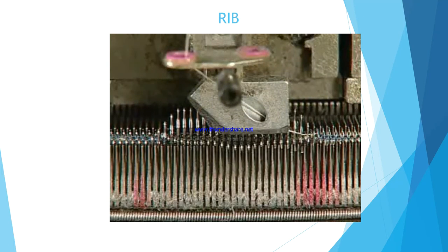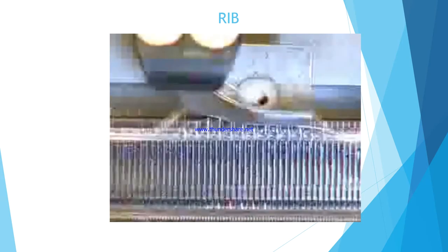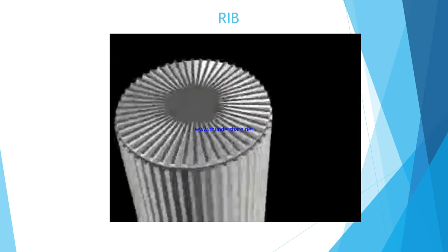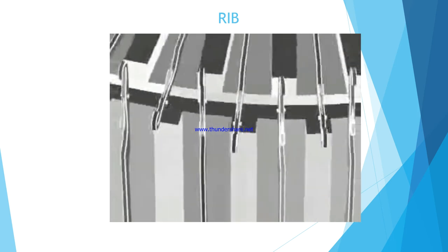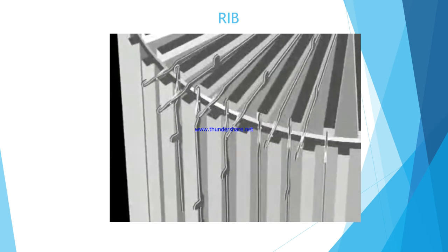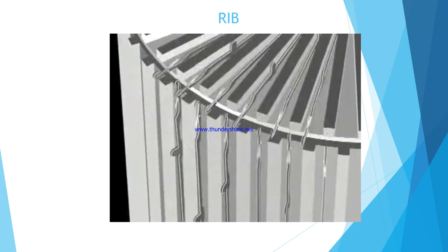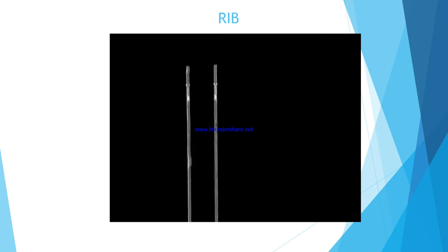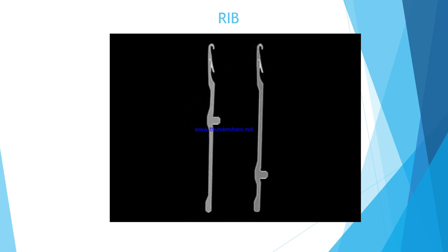On a knitting machine, needles are gated or spaced in the dial and the cylinder in relationship to each other. With rib gating, the 2 sets of needles are not directly opposite each other. The needles of the cylinder are between the needles of the dial. Here you can see how both sets of needles can knit at the same time without touching or hitting each other. Although all needles have the same length, the butts are in 2 different locations, which activates the needles to create patterning.